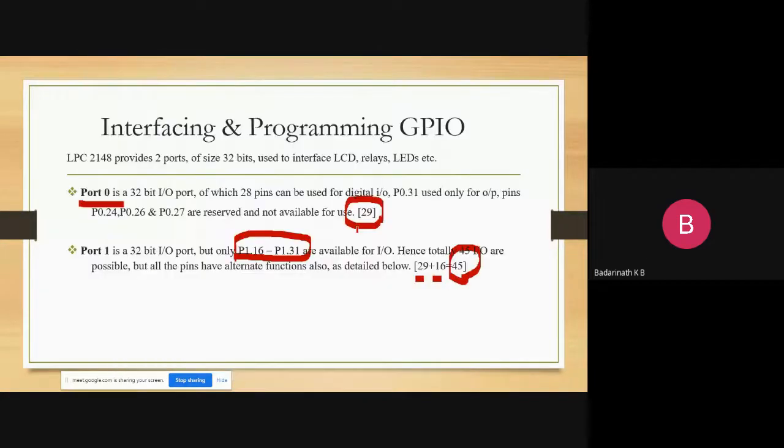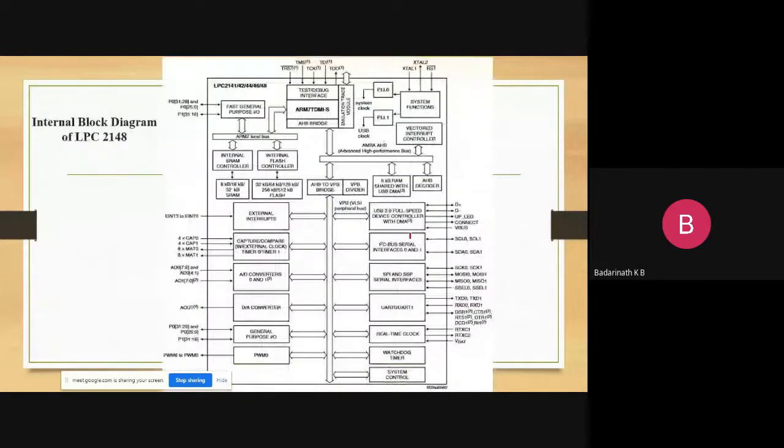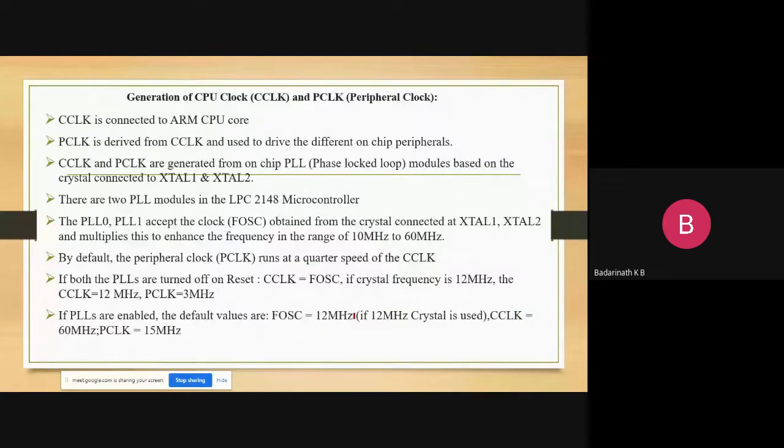If you look at the circuit, you can see that a lot of blocks are there. SPI requires so many pins, UART requires so many pins, RTC requires some pins, ADC requires so many pins. That means that 64 pins is not sufficient to accommodate all the pins provided from these blocks. There are more than about 100 or 120 pins which are coming out of the different blocks, including ADC, GPIO, and all these blocks put together. But the chip provides only 64.